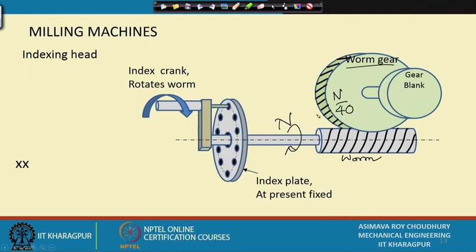So, on the milling machine table, we place a device which will be capable of providing us with equal successive rotations of this gear blank, or for that matter any such item of our interest. But first question is, why are we doing this? We are doing it for getting equal angular rotations of a body. But isn't there some simpler way of doing it? Because this seems to be quite complex.